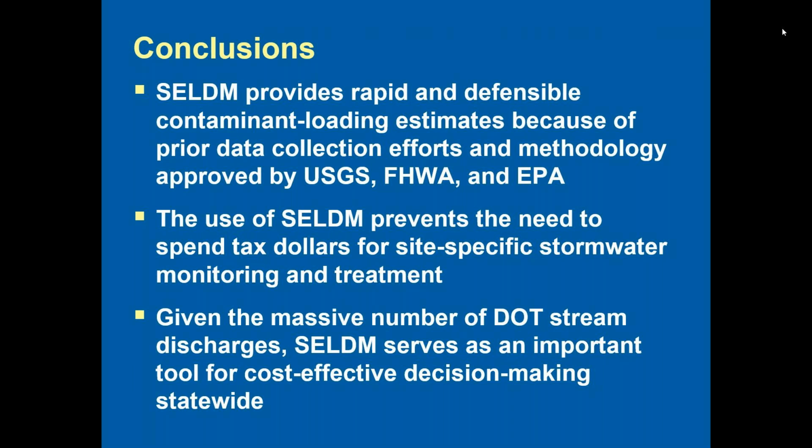the benefit of installing BMPs as you go downstream becomes less and less, because the water being discharged to has a certain concentration of, let's say, phosphorus, and even if you have relatively clean water going to it, you're still not going to bring down that background concentration of phosphorus.